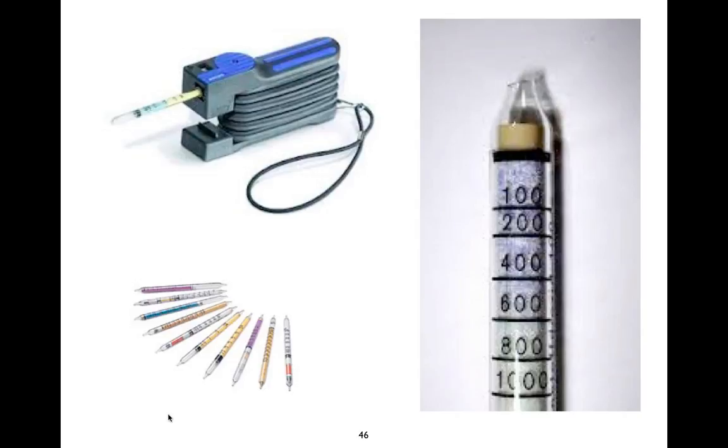And if you're really getting 20 CFM per person of exchange with outside air, you shouldn't exceed more than 700 parts per million above outdoor levels, or about 1,000. Okay, so we can actually measure CO2 levels to make a judgment, not a perfect judgment because we're not measuring it directly, but we can make a reasonable judgment as to whether or not we're getting sufficient exchange with outside air.